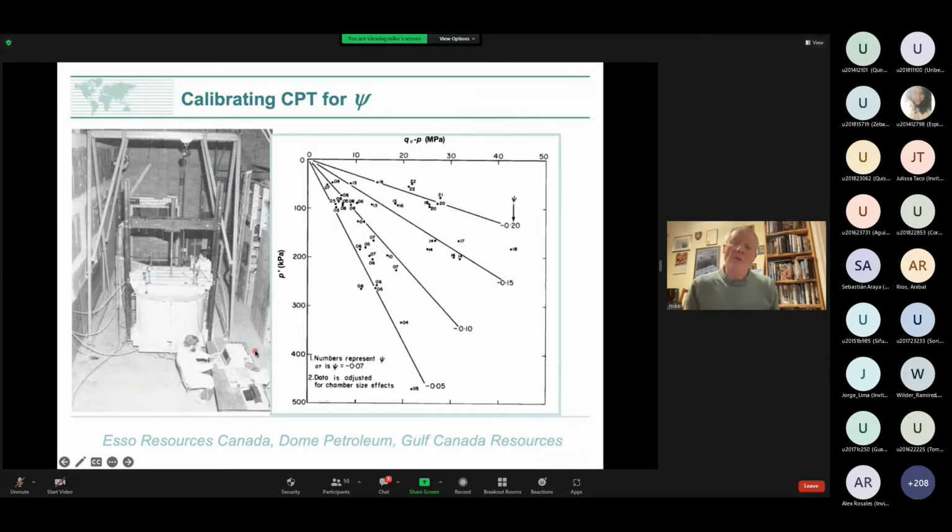And we can pick off from the trace a typical tip resistance from the CPT going to the tank. And these dots here represent a result. So, for example, if I've got a confining stress of about 80 kPa, and I've got a sand of this density, I measured about 25 megapascals.